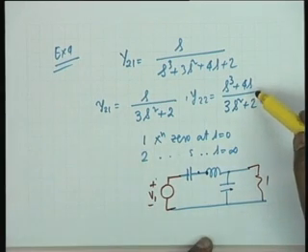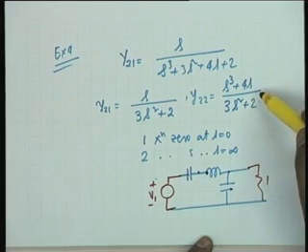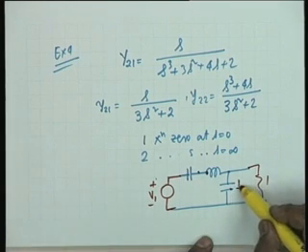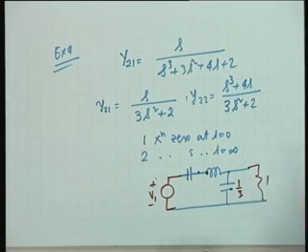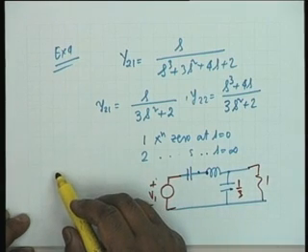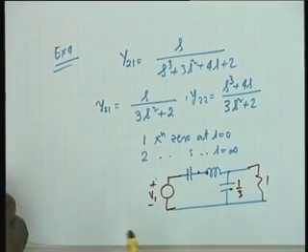All that you have to do is first to remove the pole at infinity of y22. Can you tell me what this value shall be? 1 by 3, that is correct. And if you remove this pole at infinity, all that remains shall take care of this series resonance circuit. And I can do it by inspection. You see, if I remove s by 3, what shall remain? Well, I will leave that as an exercise. I will not complete this, okay. You understand what you have to do.